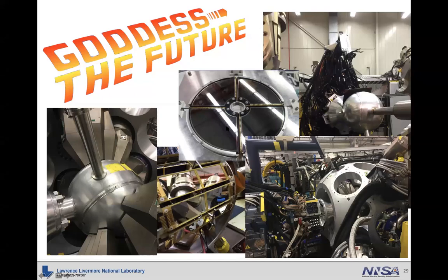This is augmented by an array of annular detectors. You can see a photograph of them here. I'm not sure if you can really see it, but they're segmented with a variable pitch on the front side. There are 32 channels, and they're segmented such that you get a degree of angular resolution from these. And the signals are brought off on these Kapton cables, which you can't really see, but allow us to maximize the coverage of silicon here. And they're segmented on the backside into 4 wedges.